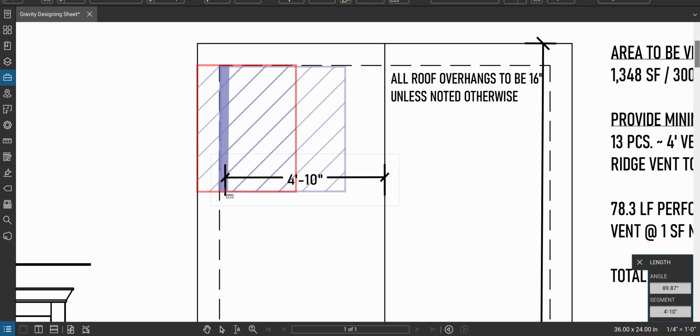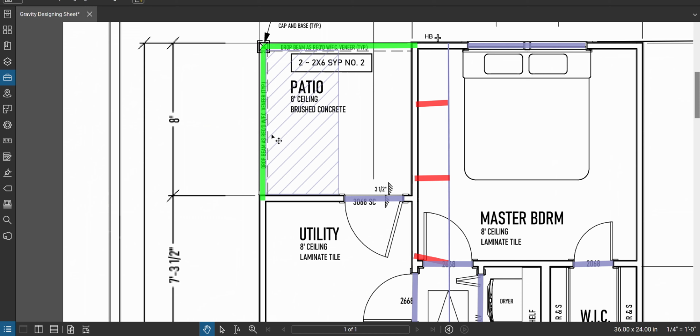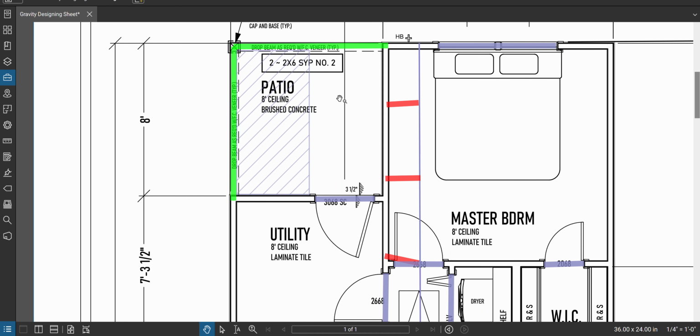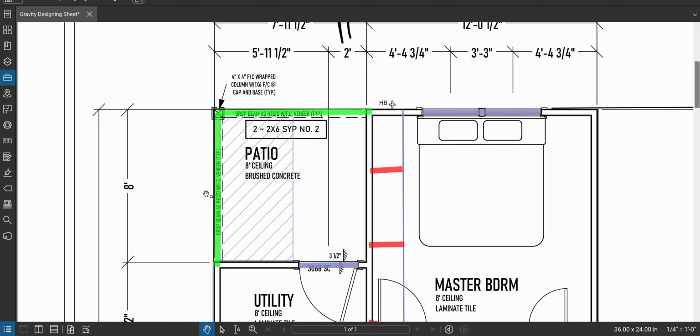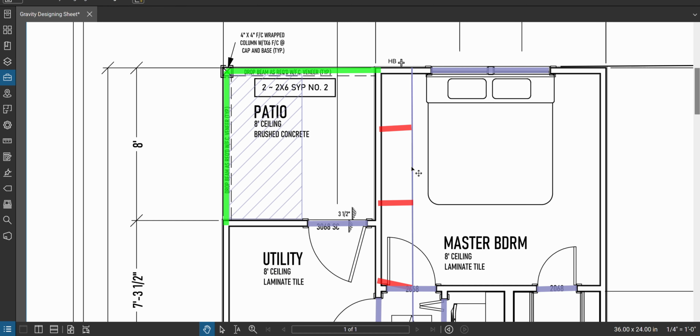So the rafters go from the wall to the ridge, and they're supported at the ridge. So I only care about half the weight of the rafters coming and sitting on my wall, and I care about the overhang. So what do I need to know? I need to know the width of this, and the width of this, just like we did the front porch. Well, it's not going to be the same thing because this wall is not the same here. So the distance between my ridge and my wall is about 10 feet, because the whole building is 20 feet and the ridge is in the center. Okay, so 10 feet from here to here, which means half of that I'm responsible for.